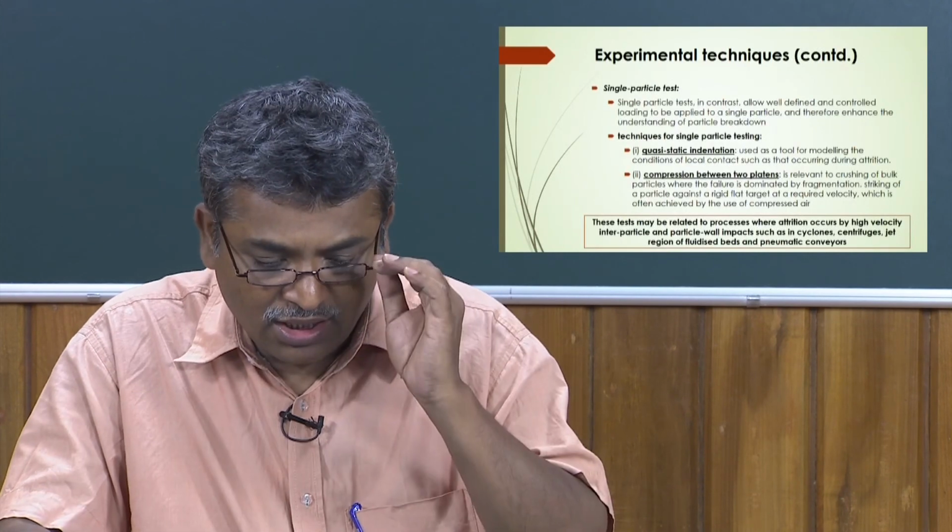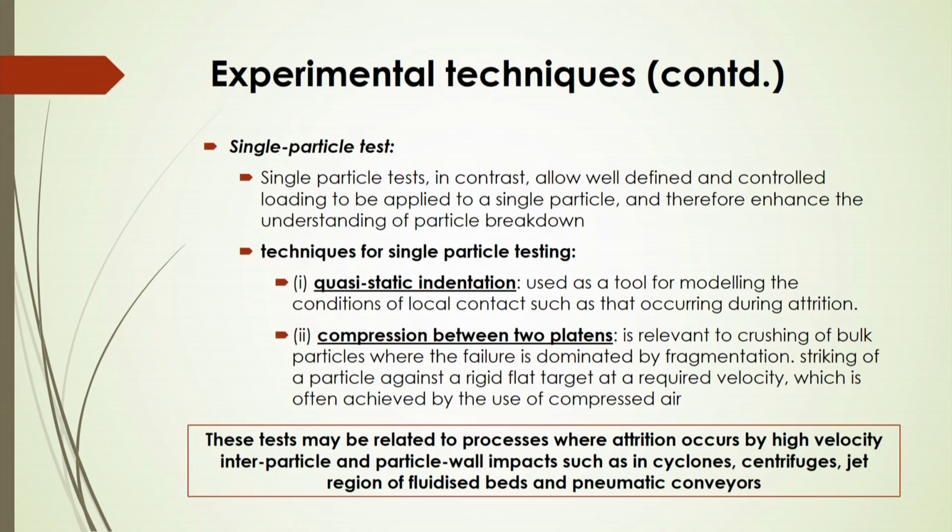And experimental techniques for the single particle test. In contrast, the single particle test allows well defined and controlled loading to be applied to a single particle. And therefore, the understanding of particle breakdown is much easier with this single particle test. There are several techniques for single particle testing, but mainly two techniques are being used.